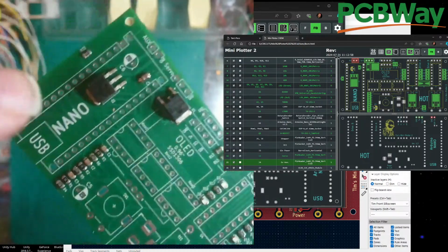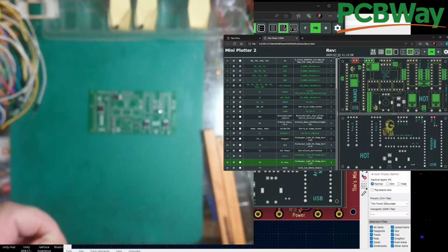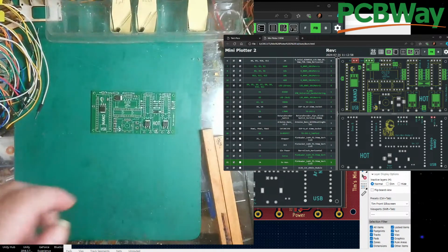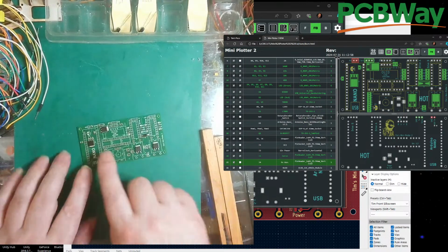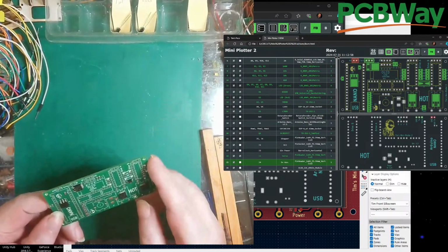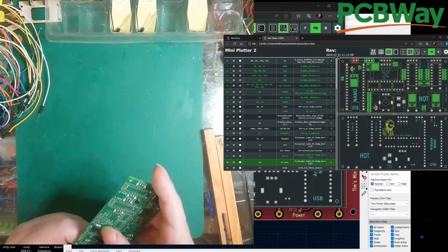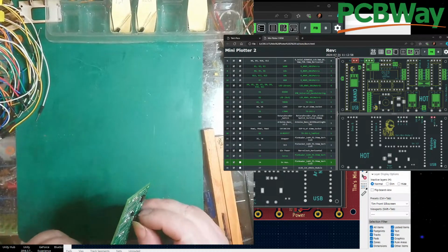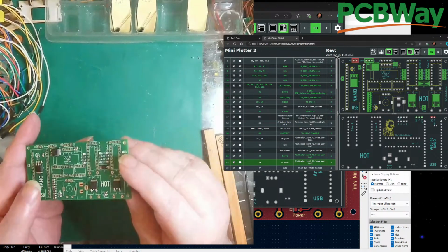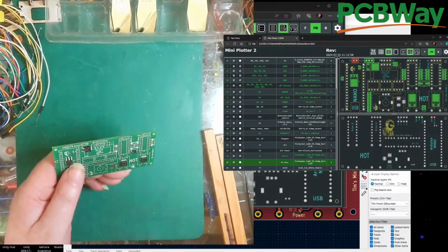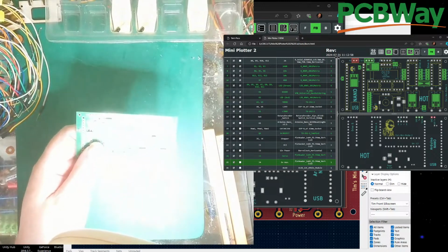So, anyways, this isn't a proper one there. This was a through hole one, and let's get back down to there. There we go. Yeah, this is a through hole component, but I've just bent it to be a surface mount, and I think I've got the right amount of solder on them big pads as well, so I think that's alright. I've got a few bits of beading. I just need to get my magnifying glass down. How's that look? Ooh, glary.